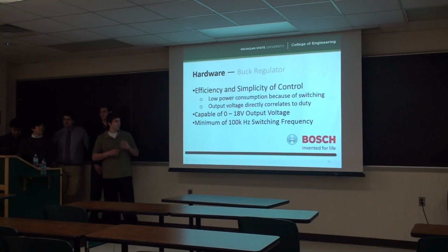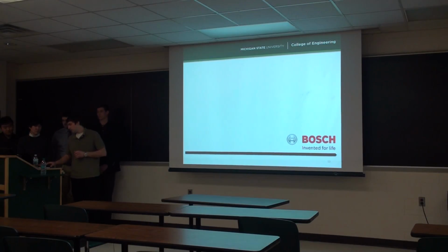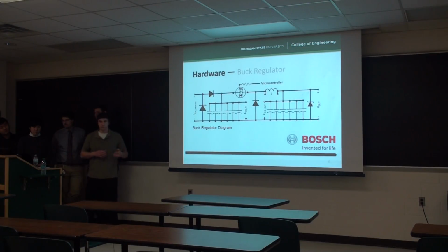And the goal is to have a minimum switching frequency above 100 kHz. And the reason for that is to filter out some of the ripple. This is the basic schematic of our rough concept.